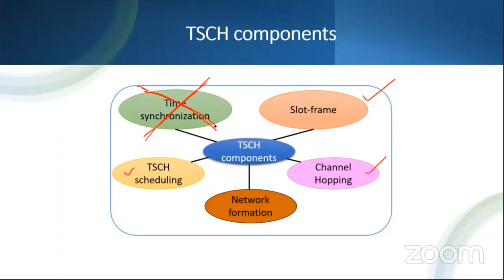They may take the IP and then integrate it into their SoC. So the IP which they get has certain performance, maybe plus or minus one LSB error in the ADC, some gain error, offset error, some differential nonlinearity, integral nonlinearity, and so on. Those errors are all characterized by that vendor, and that vendor will give the IP. Essentially, he'll give some VHDL code, which TI will take and nicely integrate into their system.